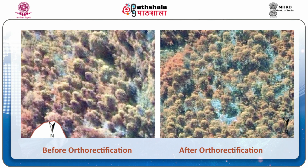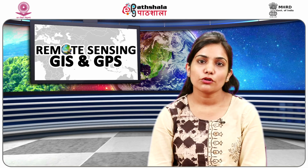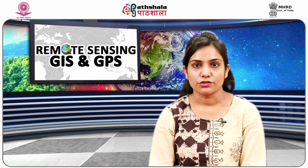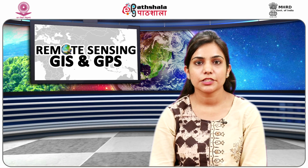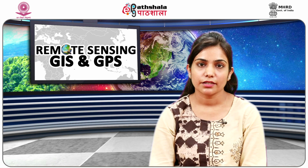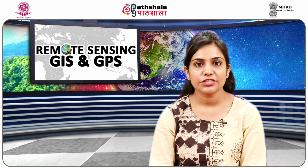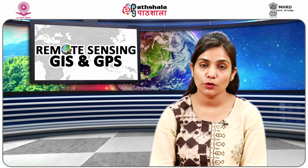Orthophotos have the benefit of high detail and timely coverage, combined with the benefits of a map, including uniform scale and true geometry. A digital orthophoto is a digital image of an aerial photograph with displacement caused by the camera angle and the terrain removed. It thus combines the image characteristics of a photograph with the geometric quality of a map.